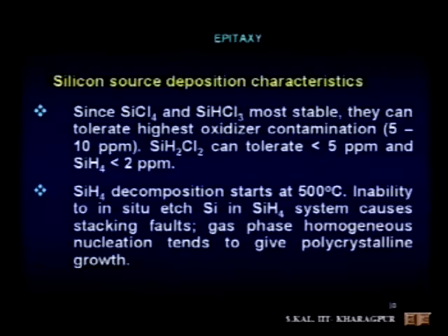That means in the SiH4 system, initially you have to send HCl gas into the chamber to clean the silicon surface, and after that again you have to purge with hydrogen gas, that is, removal of all HCl gases, and then you can start flowing SiH4 using the flow meter.